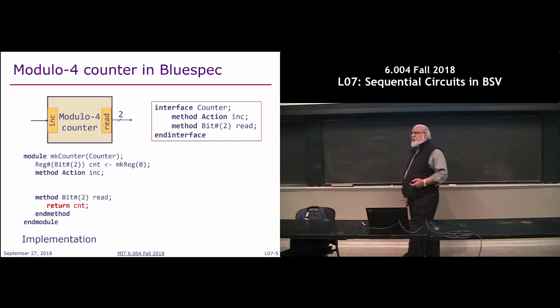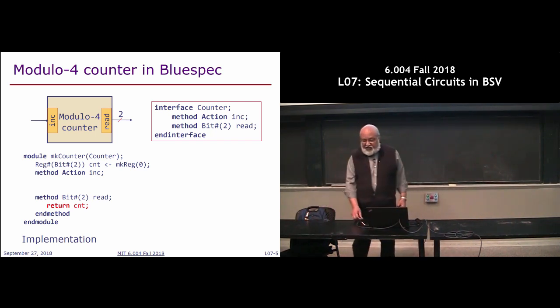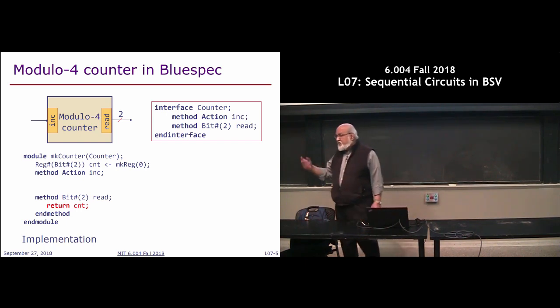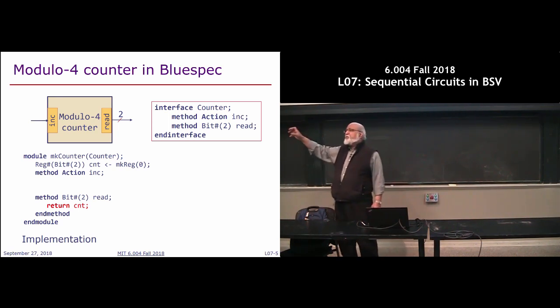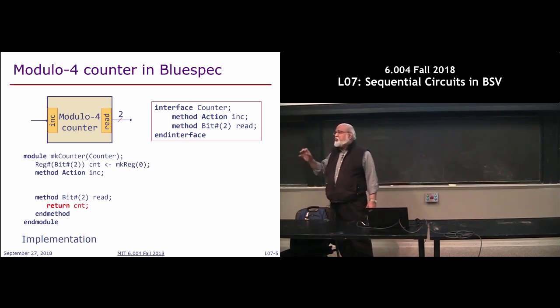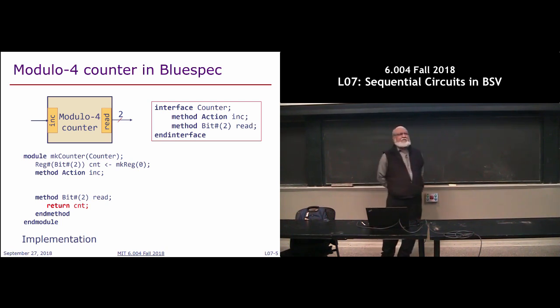So what is instantiate doing in this case? If I execute this twice, it'll give me 2 different registers. So I can say, for example, counter 1, make me a reg, counter 2, make me a reg. So these are 2 different counters. So left arrow, whenever you use it, you get a new thing. In object-oriented languages, it will be like saying a new object, right? Make me a fresh object. Instantiating it. Yep.